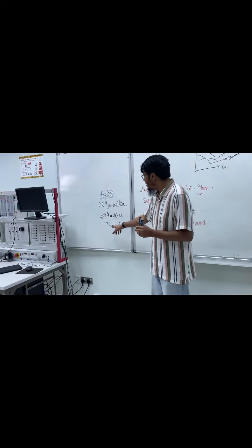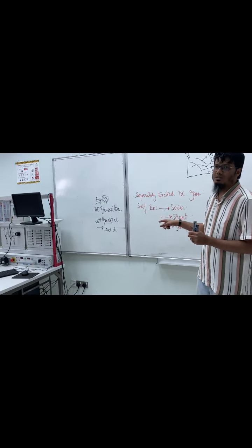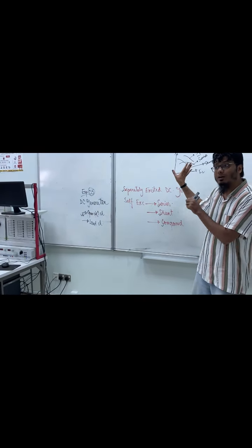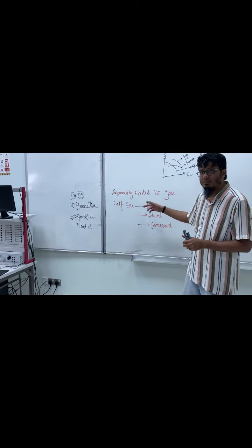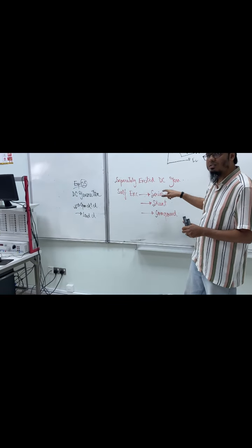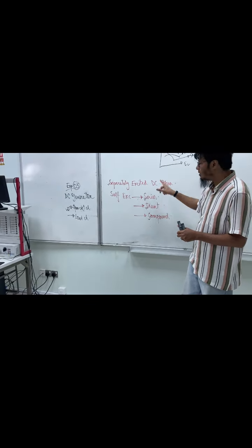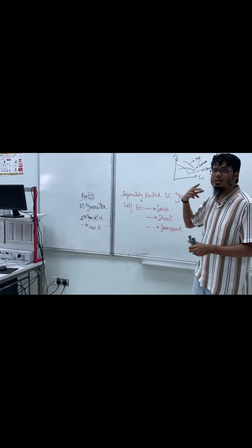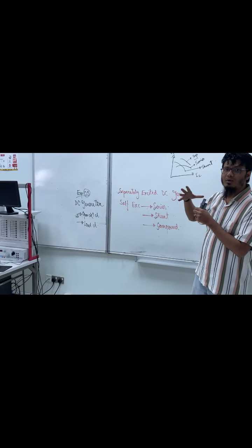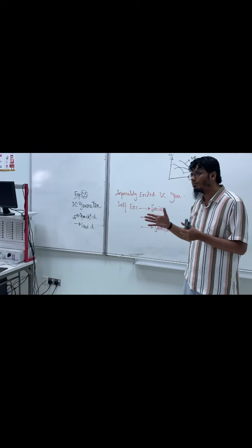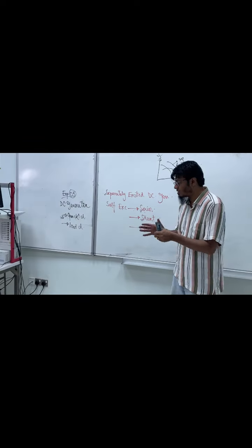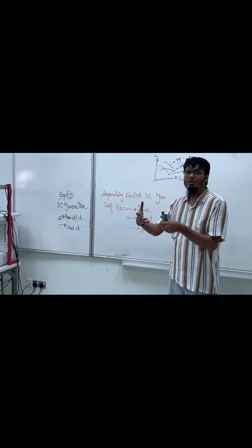So what will we do? We will do it for different types of generators. First we will do the separately excited one and plot a curve. Then we keep the curve, change the connection, make it series self-excited, and plot the curve for series self-excited on the same plane. Then we repeat the same thing for shunt and for compound. Thus we get a series of curves showing the characteristics of different types of generators, so that as a customer, engineer, or designer, if you need to know which generator to choose, you can look at the curve picture.